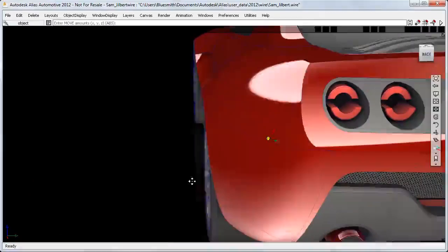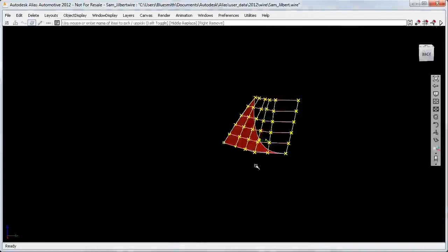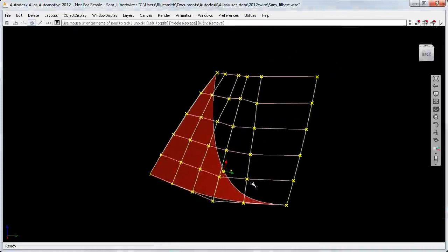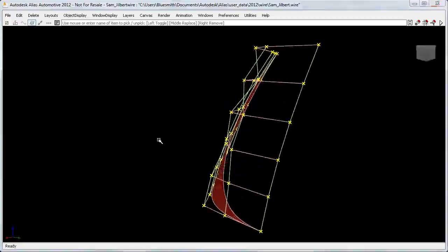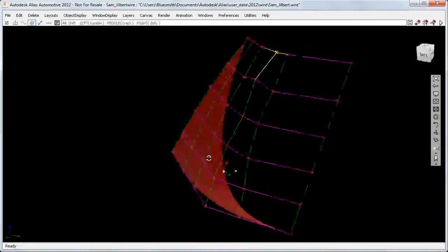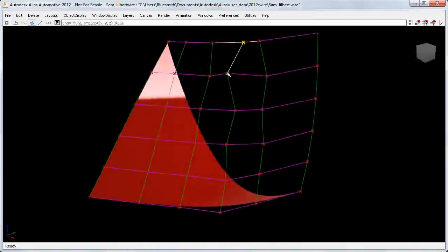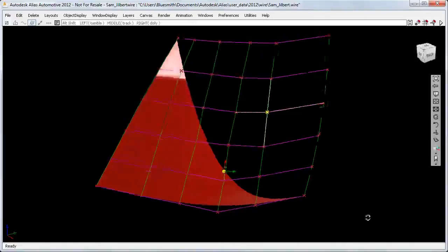If I now have a look at this more curved surface at the rear 3/4 view, it can be tricky to know which direction to work in to tidy up the surface. But with View mode I can just find the view that shows me the issues, and then quickly make adjustments. And here I'm using the first mouse button and judging the movements by eye. And this View mode is a very intuitive, free way of working, which is now added to the other more disciplined modes for Transform CV.